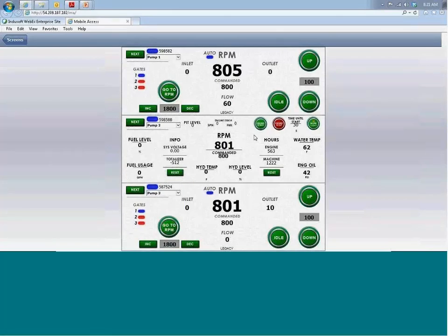The start code goes back and sends out from the cloud server right straight back to the path of the RTU that it came from, and tells the control system the user has confirmed with a security code that this pump needs to start. And a countdown starts with a warning horn for 30 seconds, which the operator can see on his screen. After the 30 seconds times out, the engine fires up and says that idle is ready for use. Engine stop is the same thing. There is no time countdown for that. We press the button. Are you sure? Yes, we wish to shut the engine down.